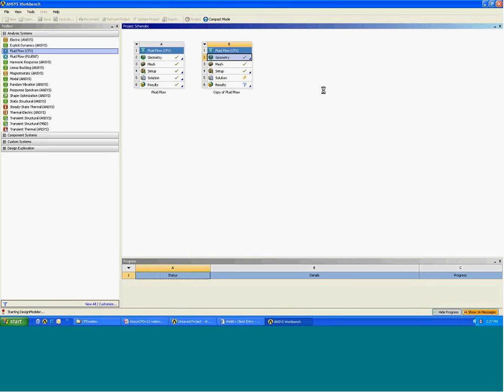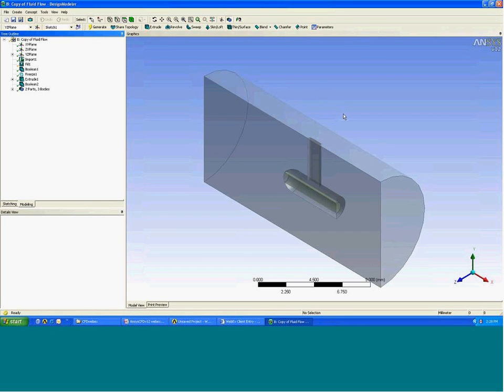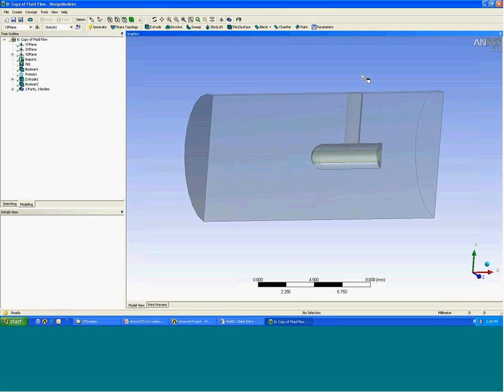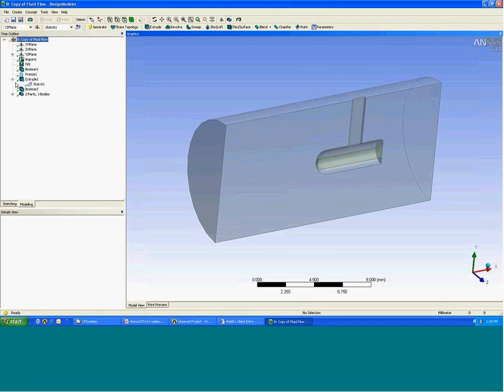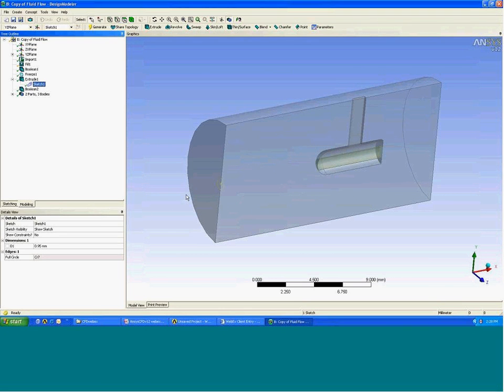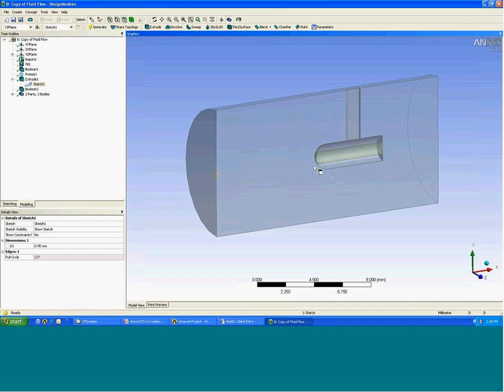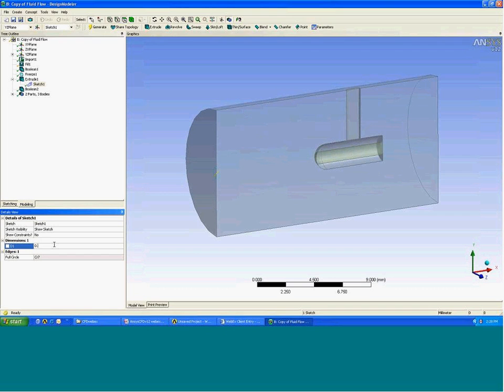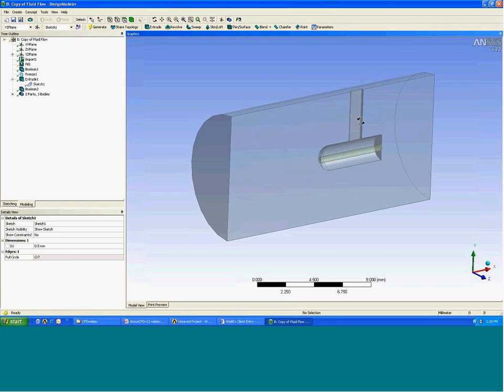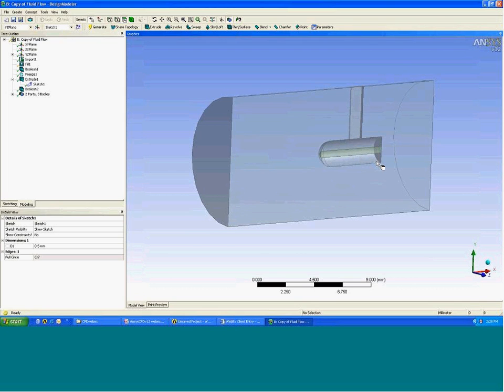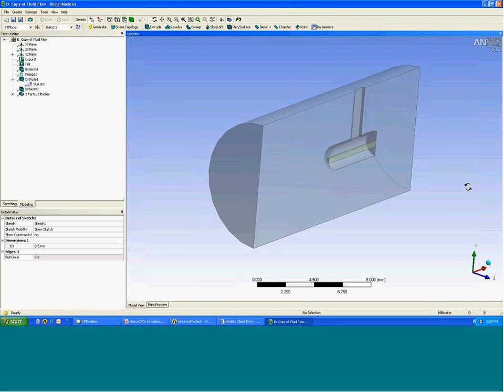I created a duplicate section of the solution that we just did from the first segment, right? So we do have the geometry file here. In here, I have a parameter to control the geometry of the internal flow passage. I can simply decrease the parameter from 0.95 millimeter to 0.5 millimeter and press generate. And as you can see, the internal flow section has been reduced to a much smaller pipe, much smaller duct. Okay, and I'm going to analyze this.